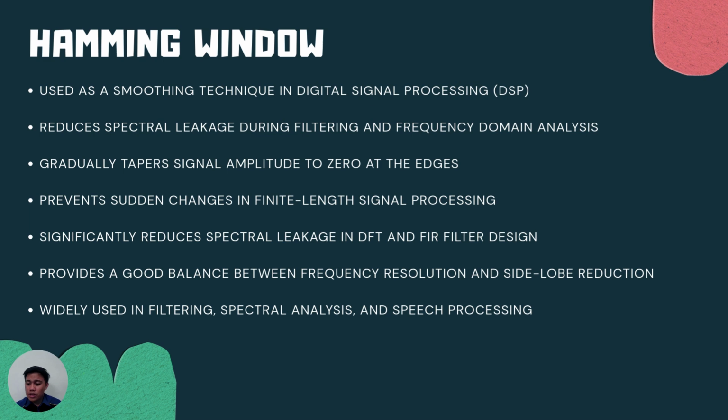This smoothing effect effectively reduces spectral leakage, especially in discrete Fourier transform (DFT) and FIR filter design. It prevents sudden change in finite length signal processing.